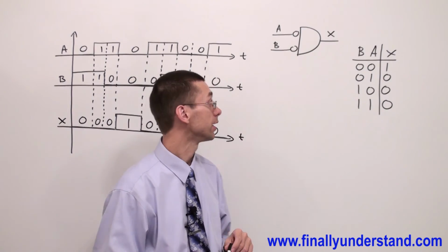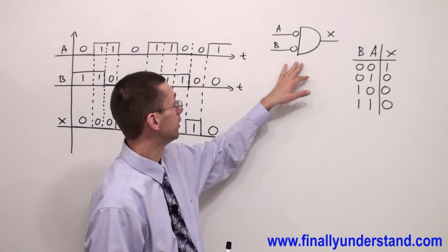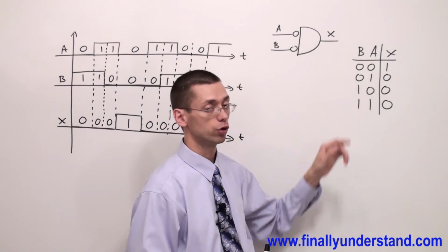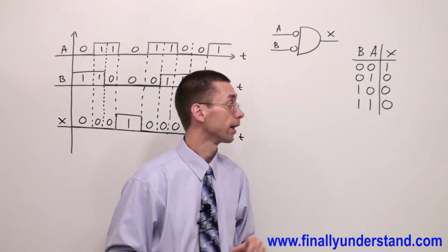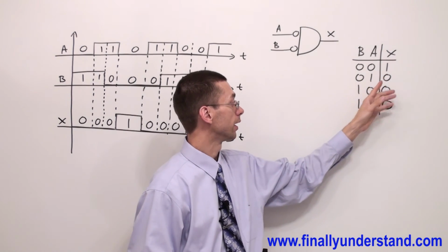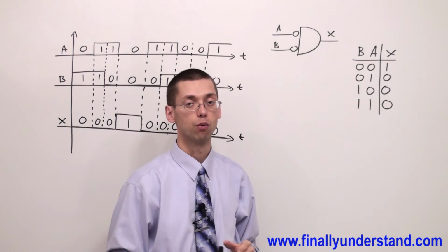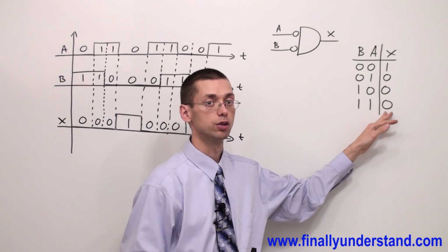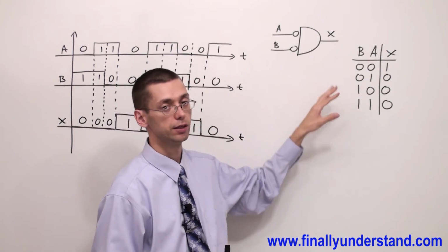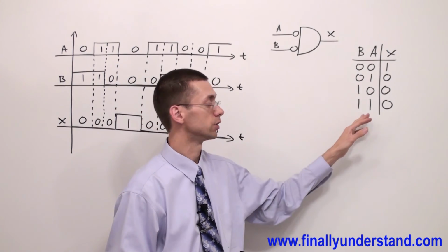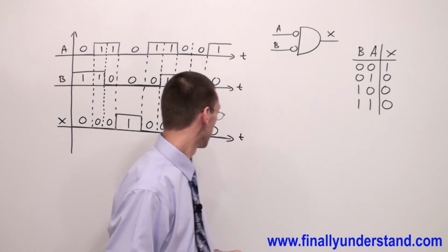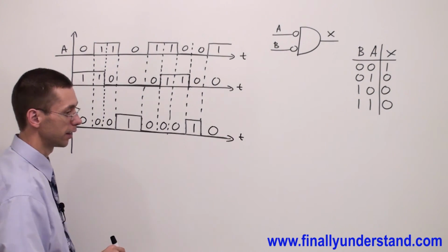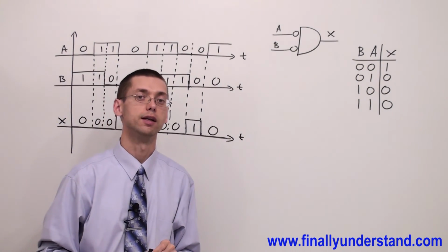If you are going to have many inputs for the negative AND gate, so if all of them are going to receive zeros, output is going to be 1. And if at least one of the inputs is going to have 1, output is going to be 0. So you don't have to remember many truth tables. You're supposed to remember just 1. Okay? And we can say that this is the solution to the problem, and we can go right now to the negative OR gate.